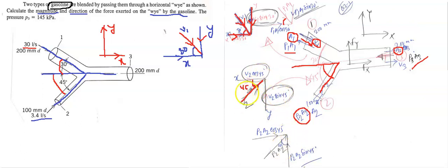Similarly, let's say instead of the velocity, the pressure force is acting there. Sorry, it should be here. It is creating the 45-degree angle here. So when it is the pressure force P2 A2 in this way, similarly for the horizontal axis, P2 A2 cos 45, and P2 A2 sin 45. Do we have any angle here? No. So that means we have the force, velocity and pressure only along the x-axis, nothing along the y-axis.